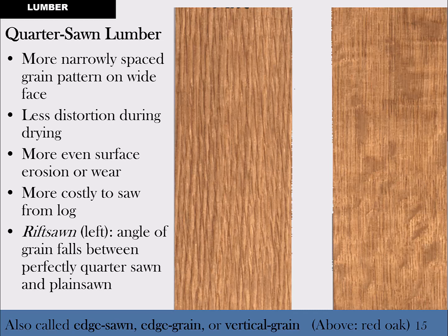Some of the blotchiness that you see on the right-hand picture is just how the stain is being accepted. Sometimes the trick to having a less blotchy stain, of course, you can put more coats of stain and get it darker and get a more even soaking through. But one trick you sometimes have to do to keep that blotchiness down is to actually use a pre-stain in order to soak through, so that the next real stain that you put on there will be more even in color. But anyways, part of that is just the staining they're doing, and the staining helps you to see the wood grain better, so that's why I guess they're showing it this way.